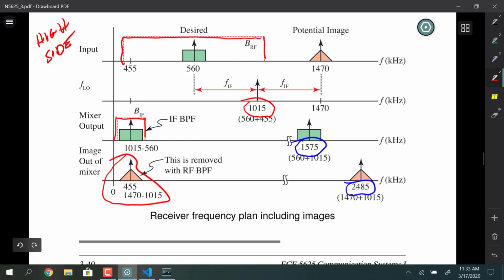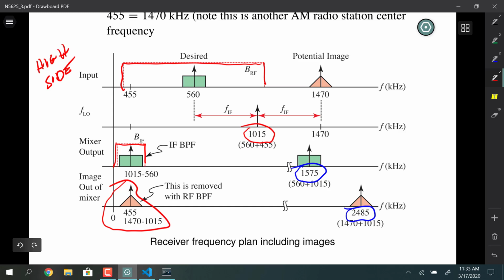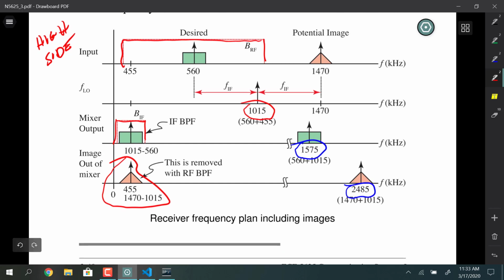So there's really two aspects in the superheterodyne principle and the frequency translation idea: rejecting images and the ability to have good selectivity, which is controlled by the IF bandpass filter, and the ability to have rejection of nearby signals that might be hanging out either side of the IF frequency. Why do I say that? It's because there's going to be adjacent signals sitting up inside of here.